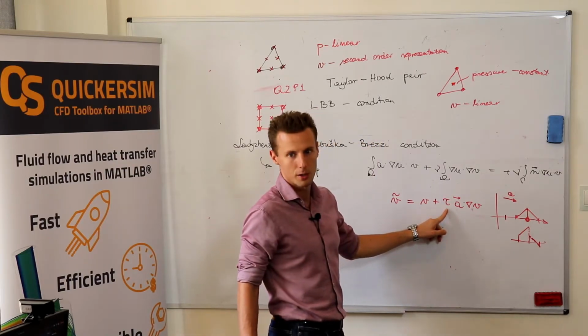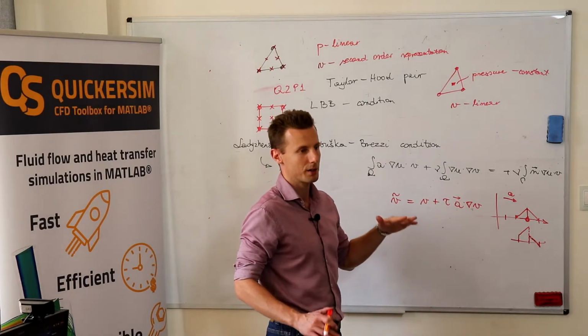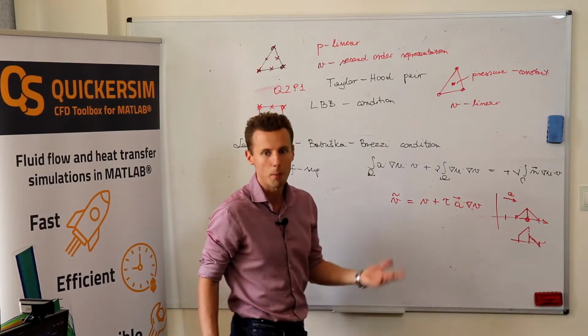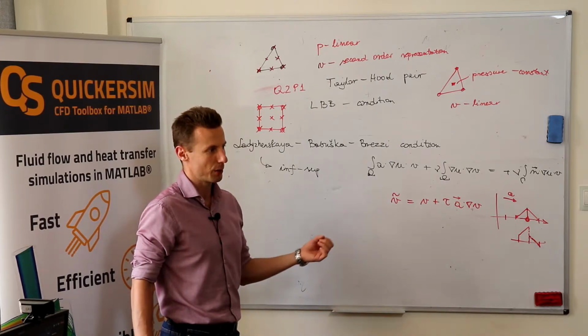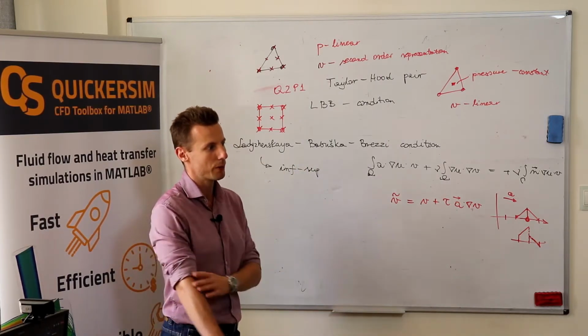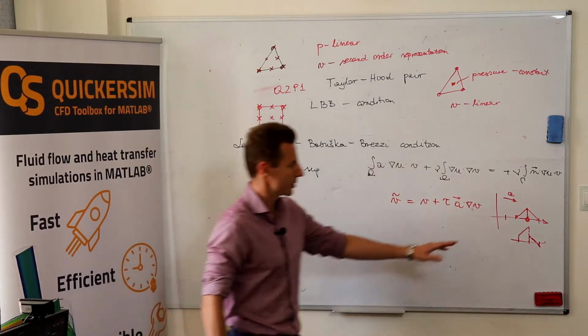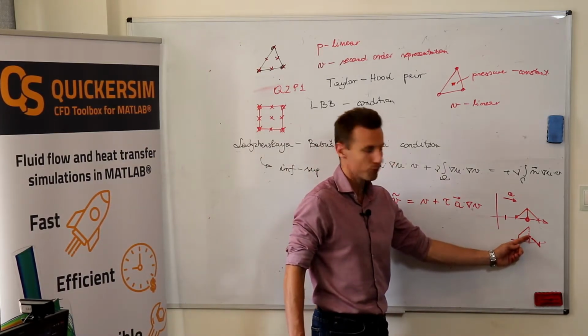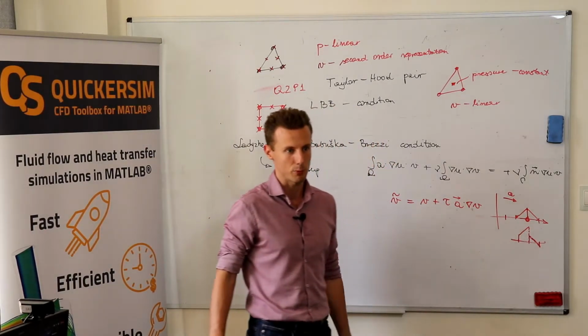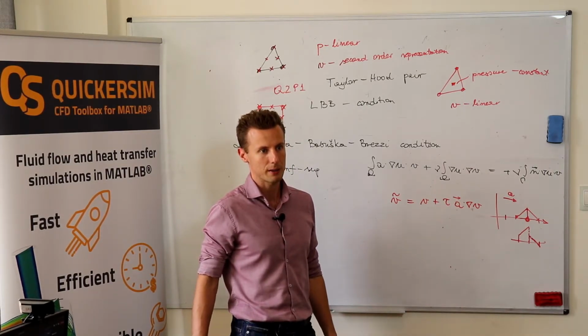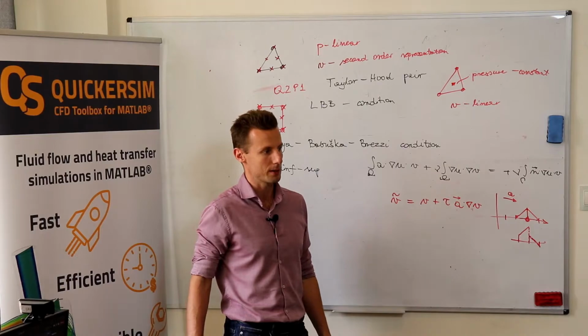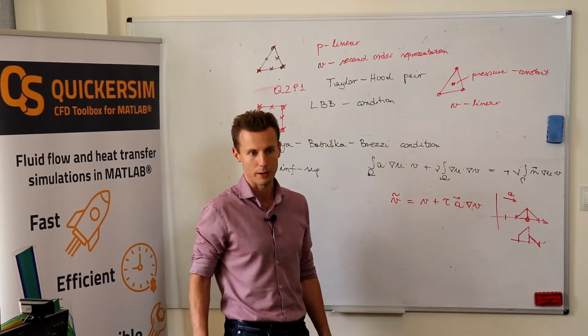This parameter is used to balance how much upwind I want to use. Do I really want to go very high with the upwind, or maybe I just want to add a small fraction to that and subtract a small fraction. Obviously, upwind for finite elements has the same properties as it had for finite differences or finite volumes.